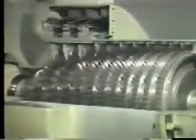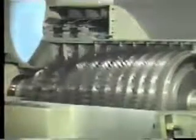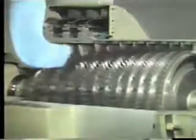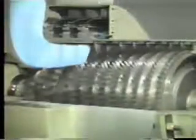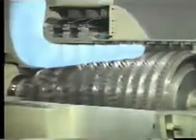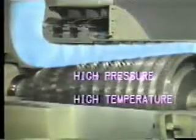Each stage multiplies the pressure obtained from the preceding stage. A very small pressure in the first stages quickly becomes a very high pressure by the last stage. Remember that the air path decreases in size along the compressor's length. This permits the compressor stages to maintain the pressure passed along from the previous stage.